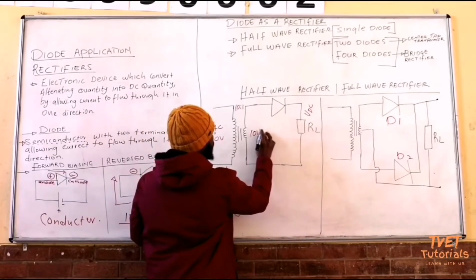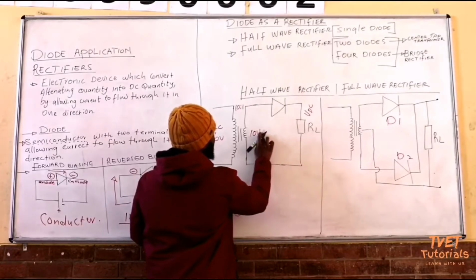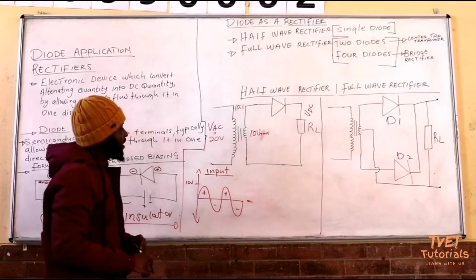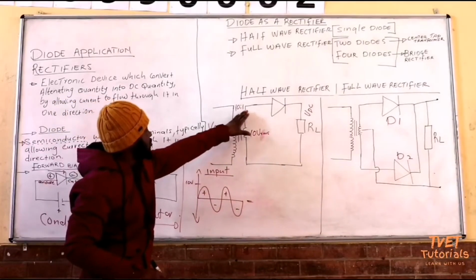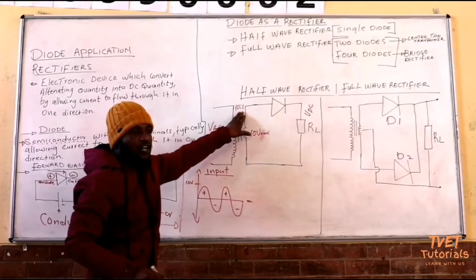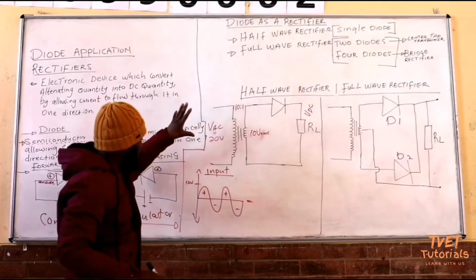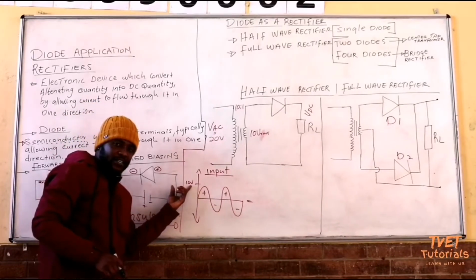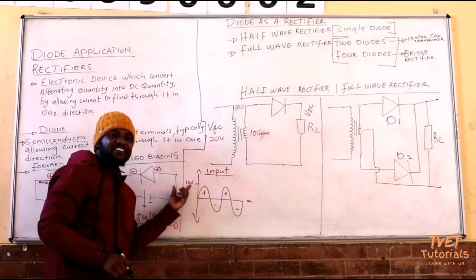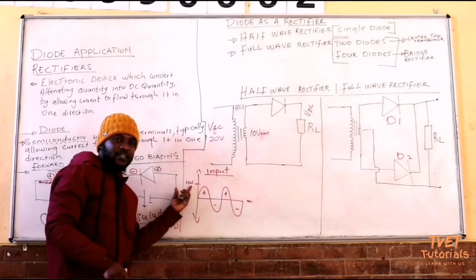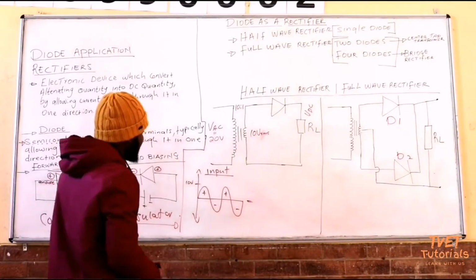As RMS. So this will be V RMS. They did not specify anything, they just gave you values 10 is to 1 and 20. And we are using this 20 and 10 is to 1, which are the turns ratio, to calculate the secondary voltage. You get 10. This 10 is also an RMS value. So you must make it a maximum. So that's what we are going to convert.